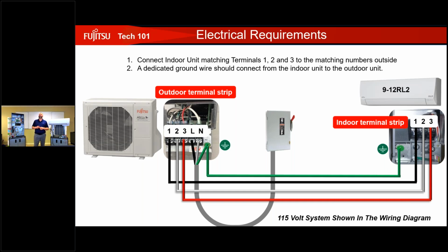So that 3-wire communicator is a signal sent from the indoor unit to the outdoor unit. That's called the forward serial signal, which we'll get into a little bit more in part 2, the ETSD portion, which we're going to be doing on Tuesday. All right, so that's the forward serial signal happening there.